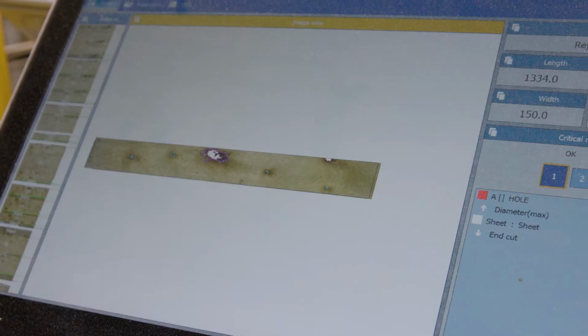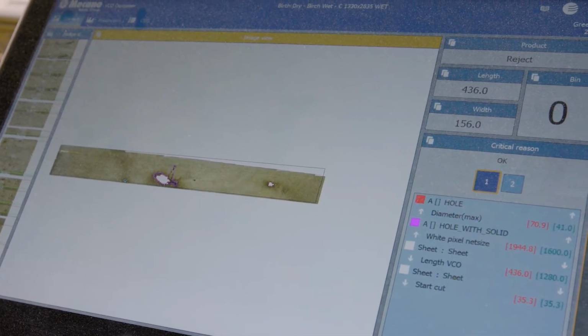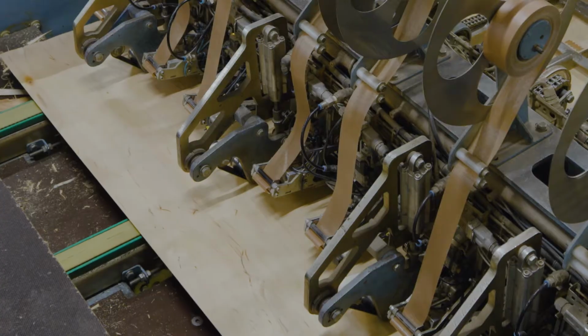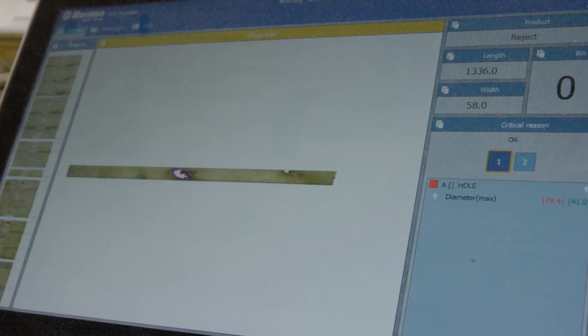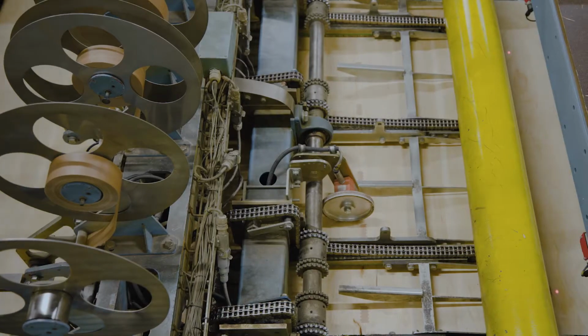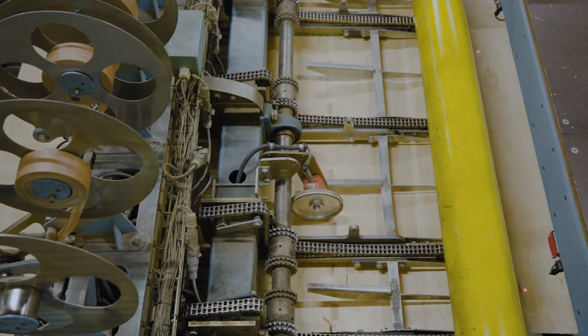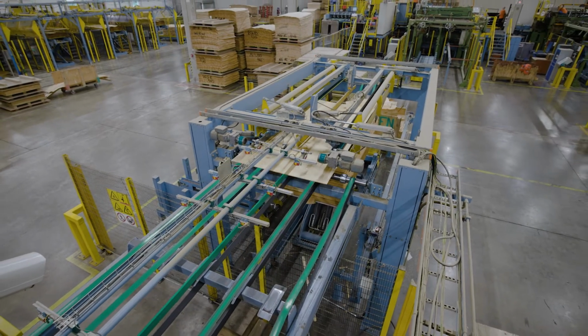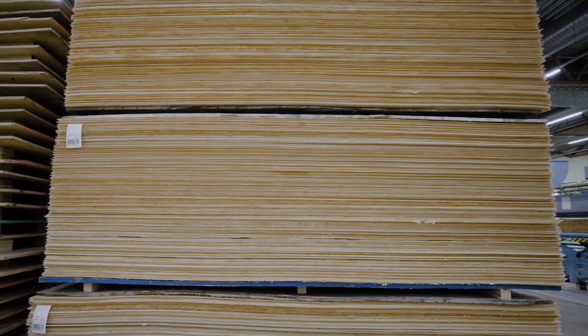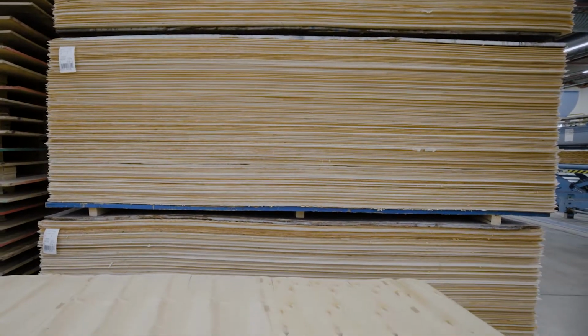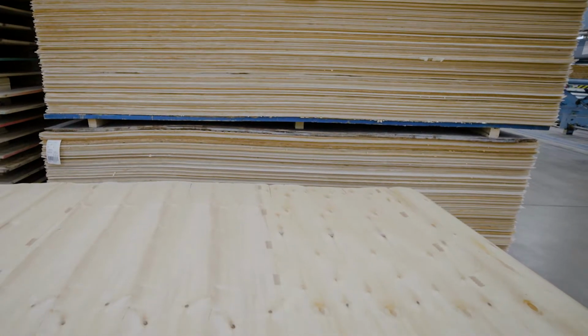As wood raw material represents the highest percentage of production costs, discarding even small veneer scraps is costly, and these should be recovered to eliminate waste. Recovery is possible through proper composing that includes intelligent defect detection and clipping. These full sheets are used as plywood core veneers, and since a single full sheet takes up less space in the veneer dryer than multiple smaller veneer strips, composing also increases drying efficiency.